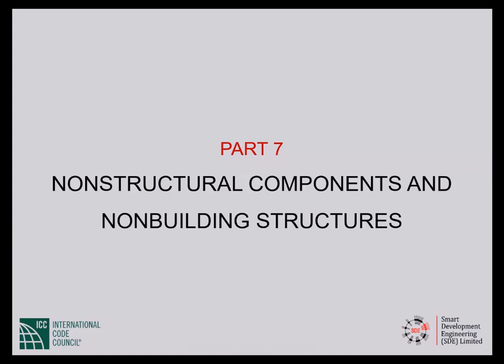Now the diaphragm flexibility, or whether it is a stiff diaphragm or a flexible diaphragm, does not depend on whether it's a steel building or a concrete building. Diaphragm flexibility is defined very specifically in ASCE 7-05.